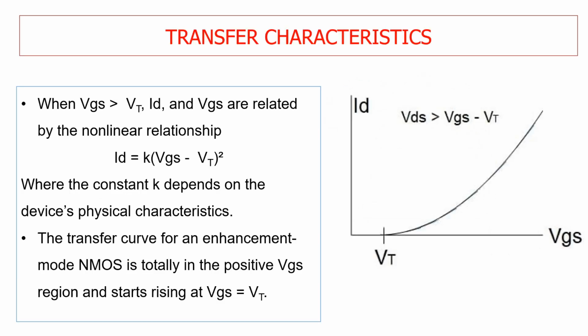Next are the transfer characteristics. In the transfer characteristics, it requires a positive gate-to-source voltage for its operation. Between VGS and ID, you plot this. It shows the characteristics. Since the drain current is 0 for VGS equal to 0, the IDS is 0 initially for this device, so the first value is 0. The gate-source voltage at which there is a significant increase in the drain current is called the threshold voltage, referred to as VT, or sometimes VGS threshold.